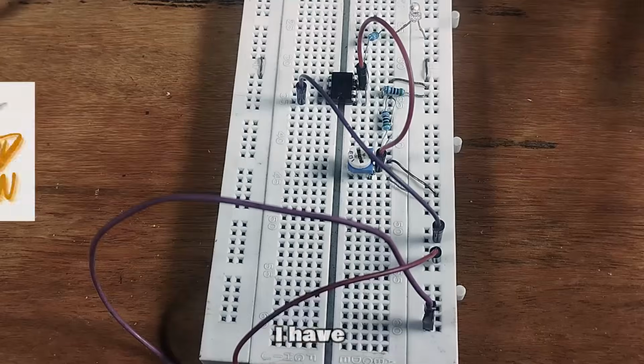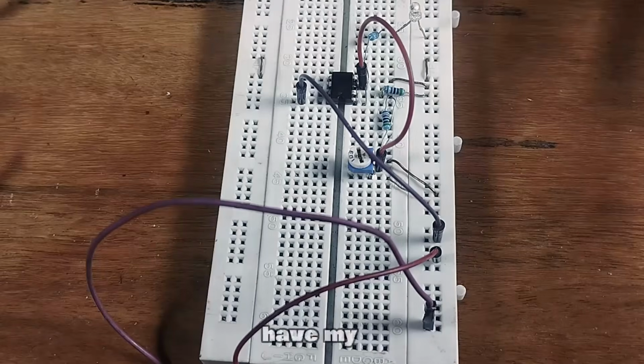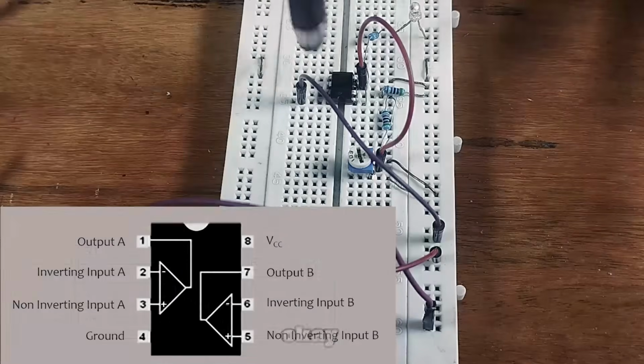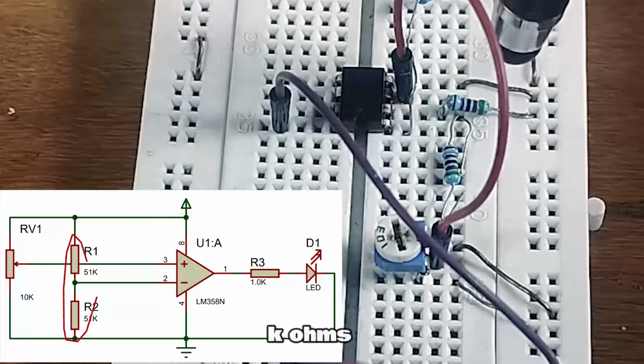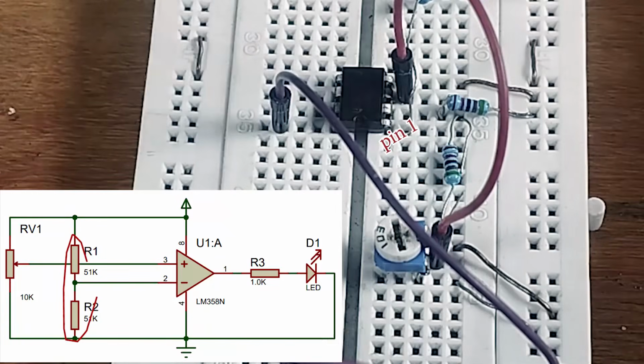Okay, so here I have my breadboard and components connected to it already. Here I have my op-amp. Alright, this is the LM358. Okay, I have these two resistors here of 51k ohms each, both dividing the voltage that will come from my power supply.